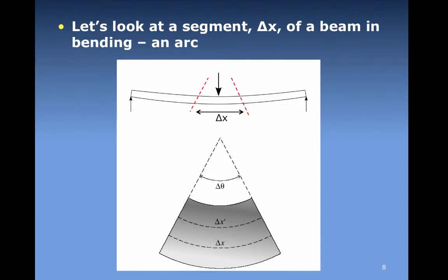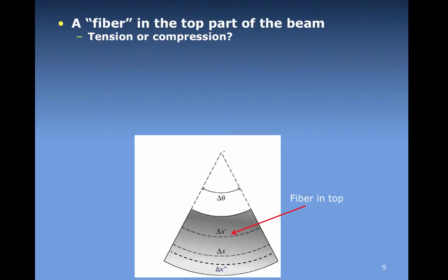And when one examines this curvature, one can look at different fibers that appear along the thickness of this beam here. Again, if we look at the undeformed shape, this would look like a rectangle. As we apply moments, this curvature becomes apparent, and we can track the relative length of fibers along the thickness of the beam.